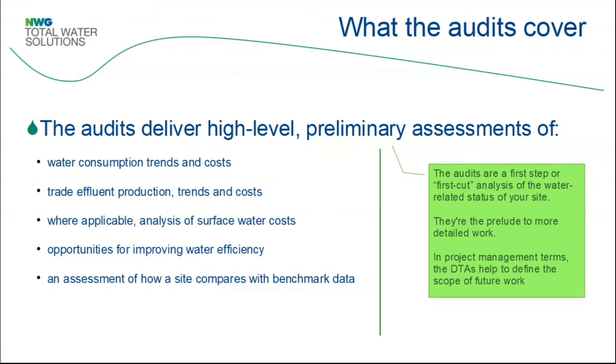Now, they hadn't noticed this. They didn't know this had happened. They'd been given no notification of it, and they'd gone onto this fixed strength charging mechanism, and it had greatly increased their costs. And the reason it had greatly increased their costs is because the water company who had managed the trade effluent, which wasn't Northumbrian Water, I hasten to add, had taken a very small number of samples, worked out an average composition, and then assumed that average composition would apply for the forthcoming 12 months.